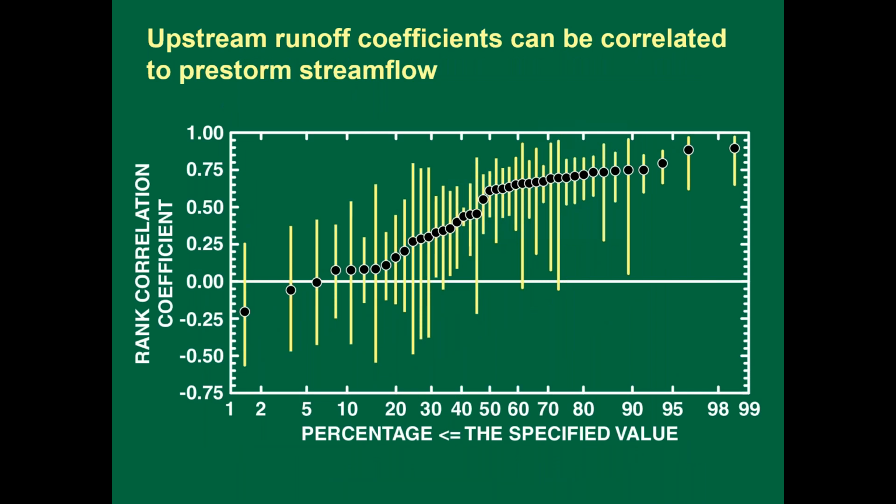So when we were designing SELDM, we wanted it to reflect how data looks in the real world. If you look at the curve numbers that EPA uses for several of their models, you have the antecedent wetness. So we looked at a lot of the literature and available data to try and figure out how we can simulate the effects of antecedent wetness on runoff coefficients.